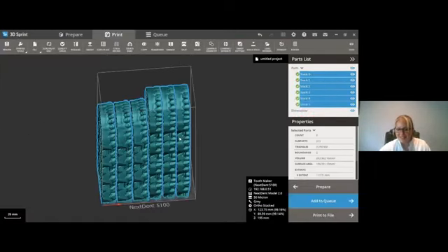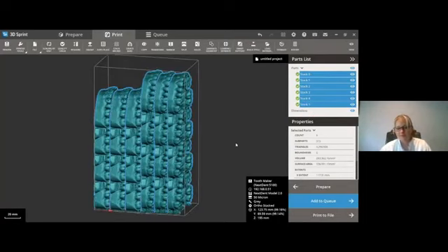Well, are we talking about this down here? Go ahead. Yeah. So these scaling values are of course hard coded for all the materials, but can be optimized if you use that scaling and offset algorithm to print these test blocks. They come from measuring test parts all over the build platform, and they compensate for the material shrinkage, but also there is a factor for the light source and for the DLP chip in there.